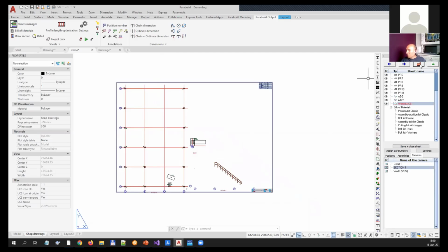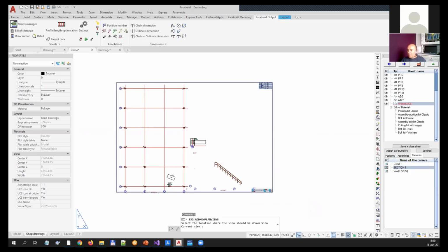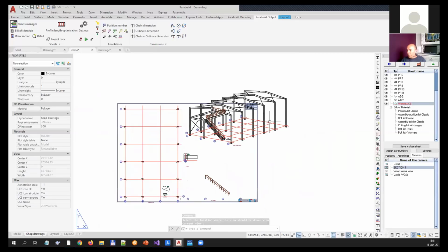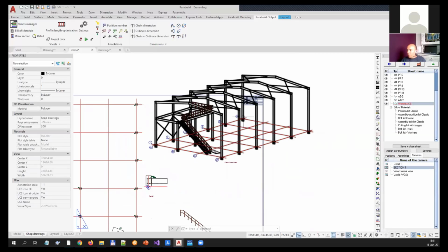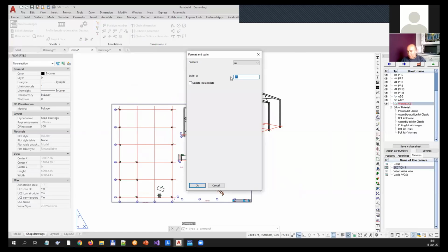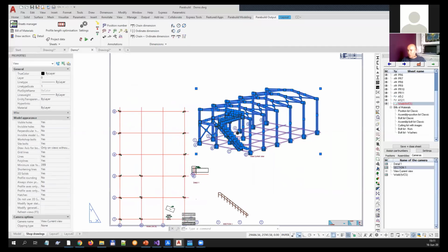There is another way to do the same. So for example, let's generate a new view, and I'm going to choose current view. Current view really means the current view in the 3D model space. So if I do that, then I should see a view of my 3D direction. Yeah, so that's what I had been looking at. Okay, so this view is now too large for the page. We can just right click and change scaling to fix that, for example. Or we could change the scale of that view, of course. That would be a solution as well.